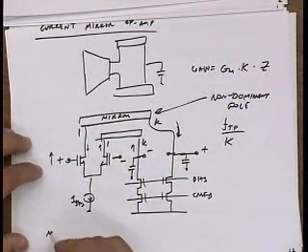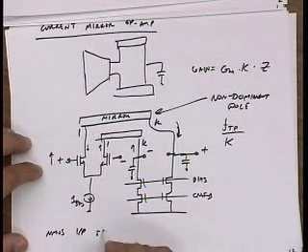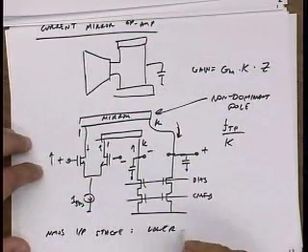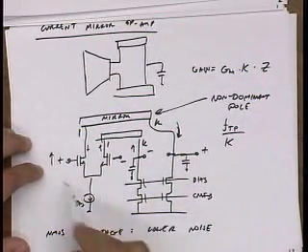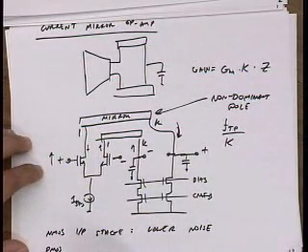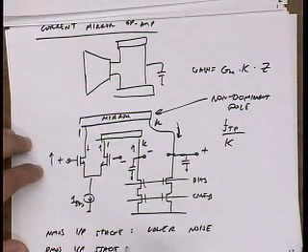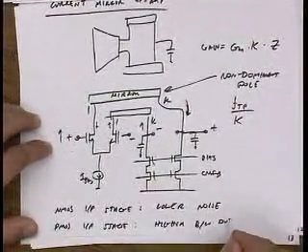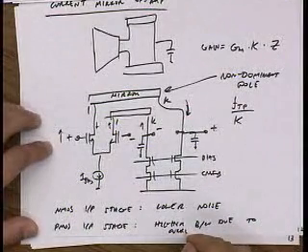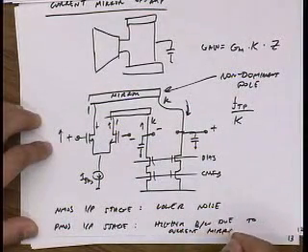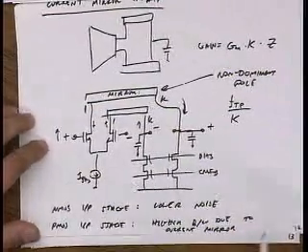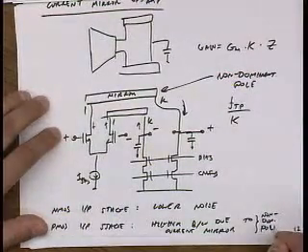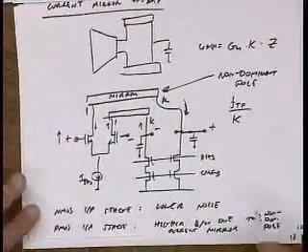So an NMOS input stage has the advantage of having lower noise because the gms are larger, right? But the PMOS input stage can give you higher bandwidth. And that's because of the current mirror, because we need the opposite polarity current mirror. Higher bandwidth due to current mirror, and this is due to the non-dominant pole. And then, as you mentioned, the flicker noise is going to be better for the PMOS.